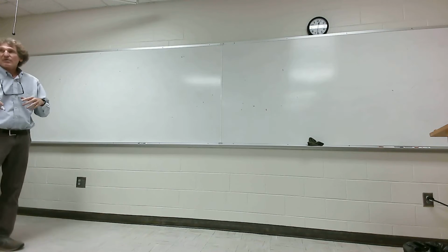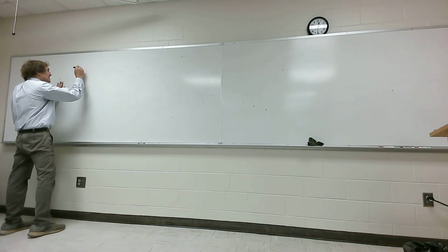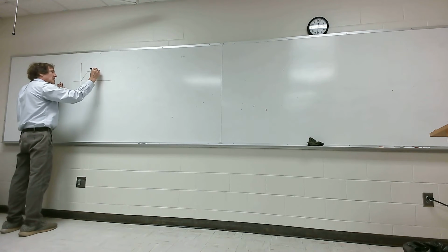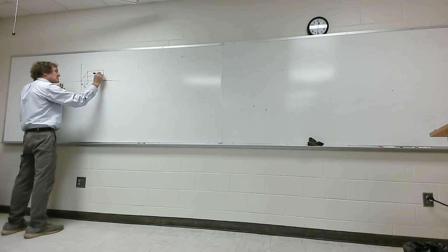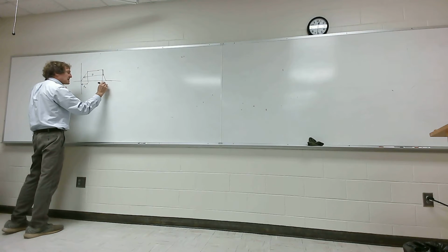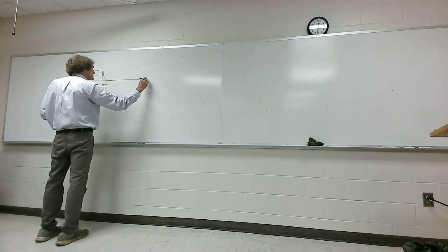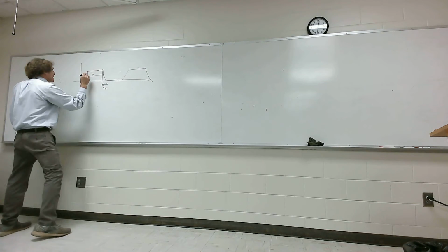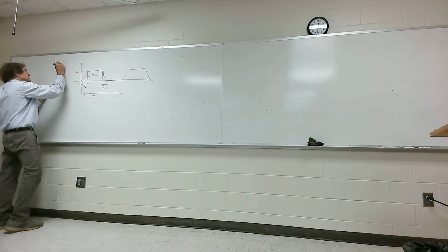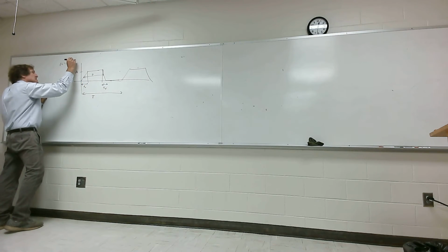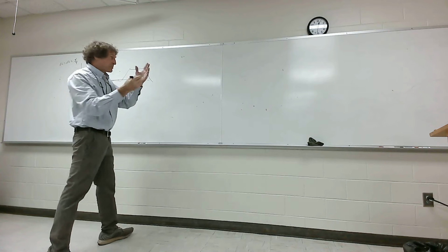Okay. Back to this thing. So now we're going to get into the actual frequency spectrum of this waveform. So when we have this waveform here with a rise time, fall time, this has rise time, tau rise, and on time of tau. Fall time equal to rise time, tau rise, at a given period T, at a height A, duty cycle equal duty time equal tau over T. So we come over there and we had those coefficients.